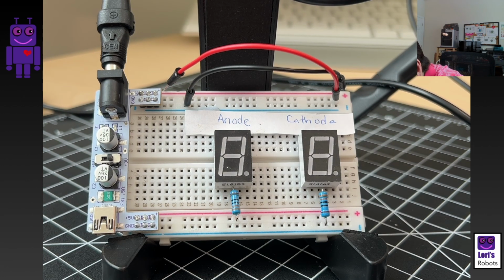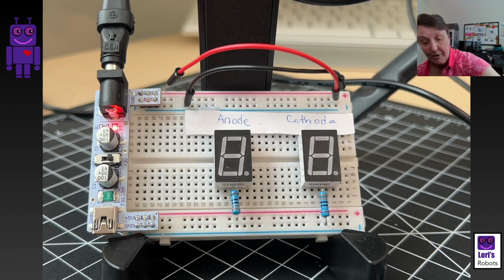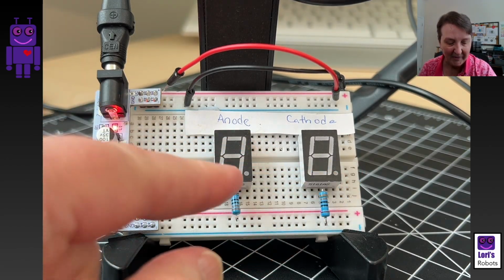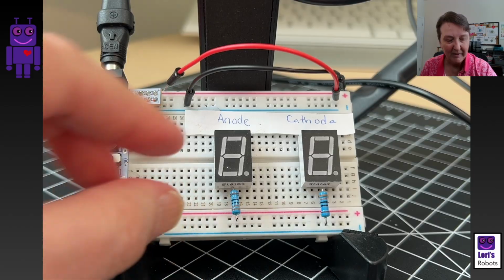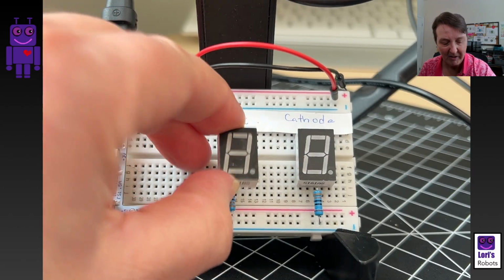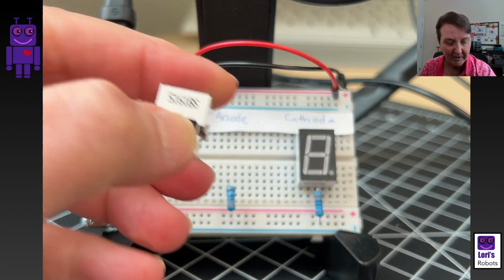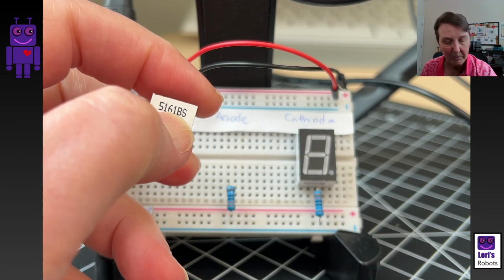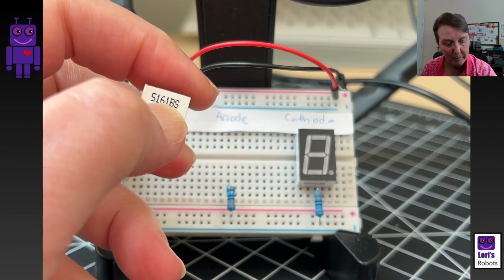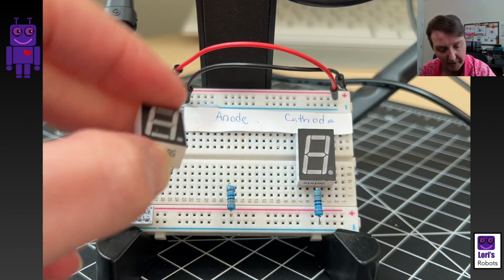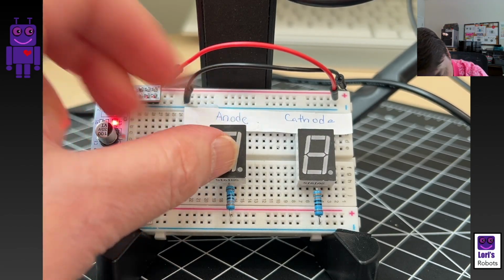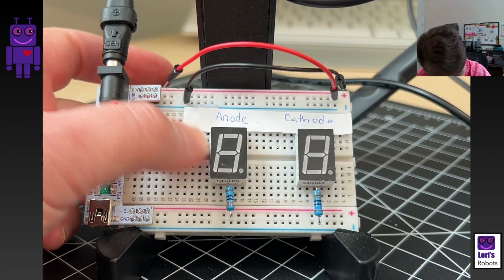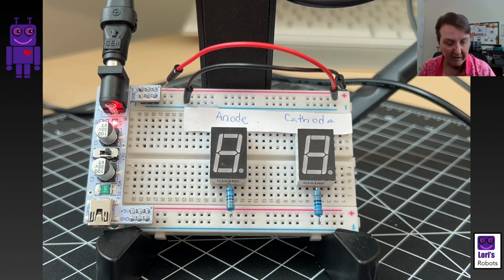I know that this is an anode and this is a cathode, but I did have to experiment. Sometimes you can tell by the writing on the side. It turned out in the writing on the side of these things, if it had an A in this number, it was a common cathode. If it had a B, it was a common anode. But I certainly didn't know that going into it. Make sure I got it back in the right spot.